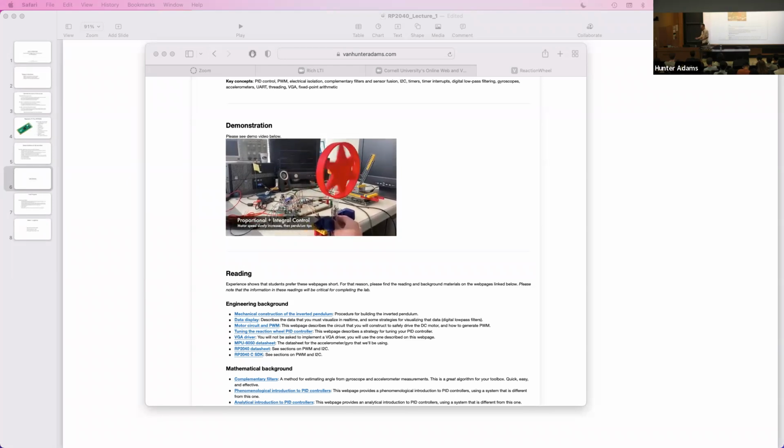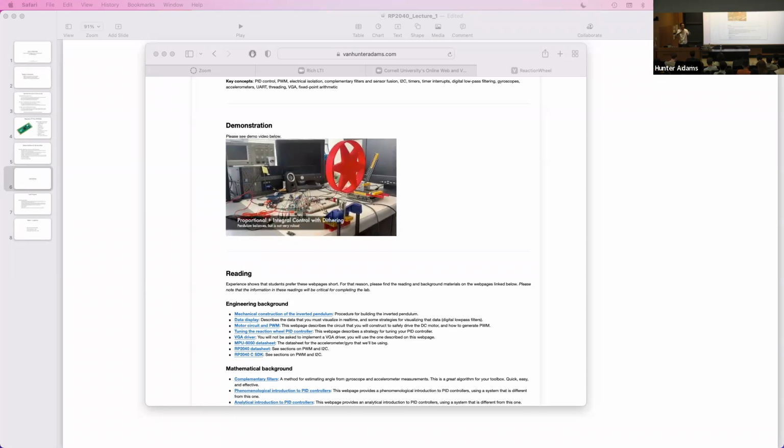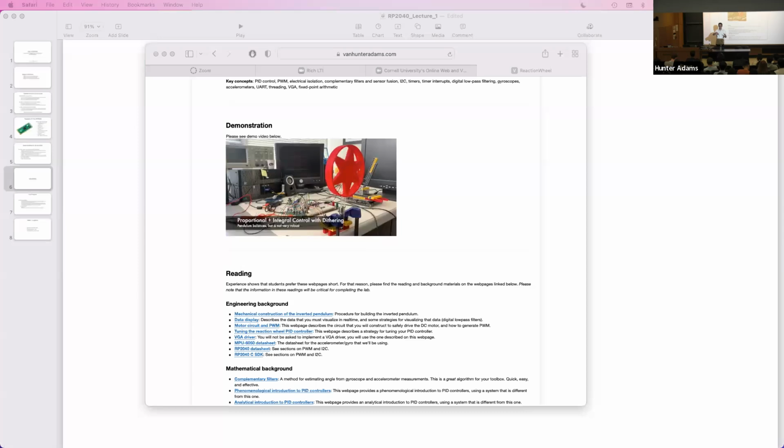What a reaction wheel is: you take a heavy disk, and you rigidly attach it to the spacecraft so that the disk and spacecraft are considered one system. Imagine the spacecraft is a cube, with a disk sitting in the bottom, floating in the vacuum of space. You start spinning the disk clockwise. What's the spacecraft going to do? It spins counterclockwise. It has to conserve momentum, right? So you take one of these and point them in each direction, and you have 3-axis control of the spacecraft.